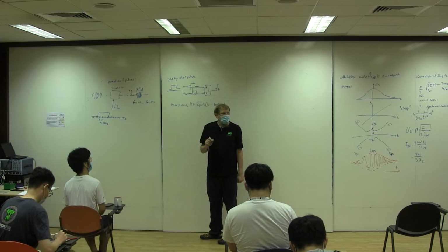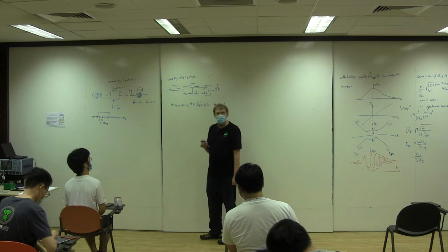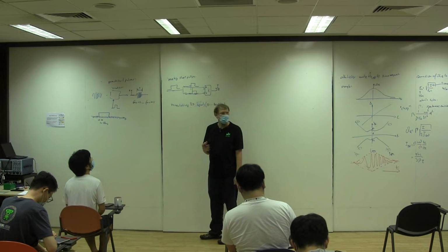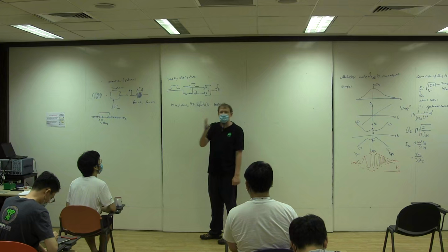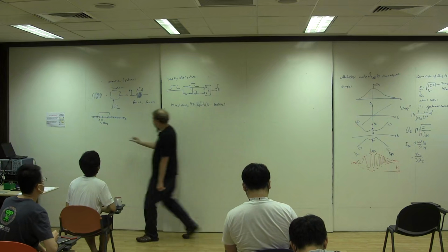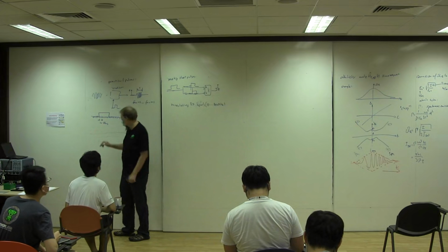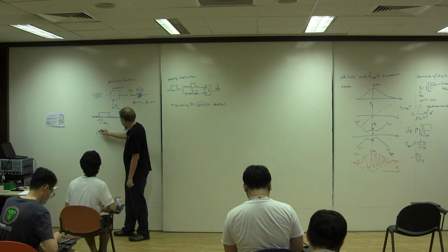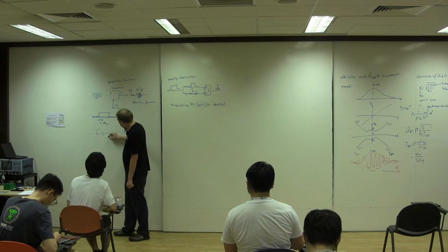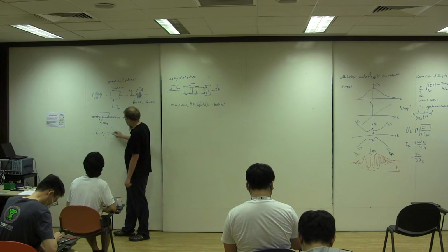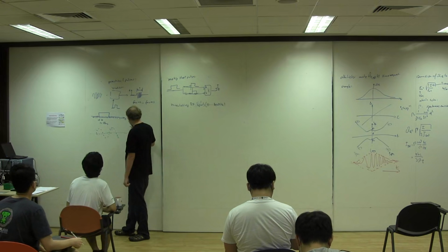One way is, if you have low enough frequencies, you can do this these days with a direct synthesizer. A direct synthesizer does something like that here. It works in a time discrete way, and it just generates the sine wave or an arbitrary waveform, whatever you want to have. So in a time discrete manner, it tries to synthesize a sine wave with time discrete samplings of it. So this would be a synthesizer.